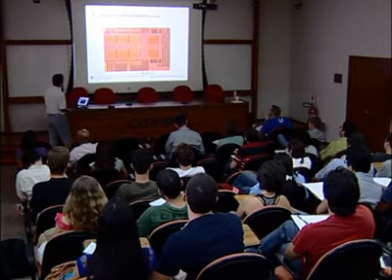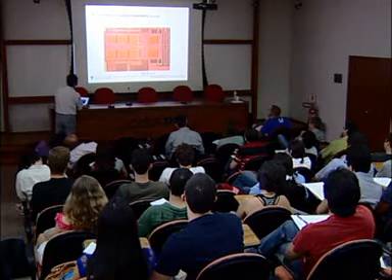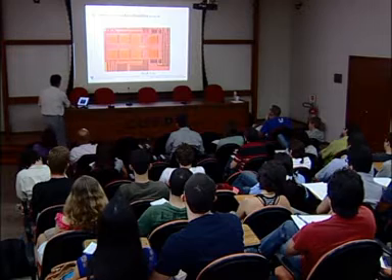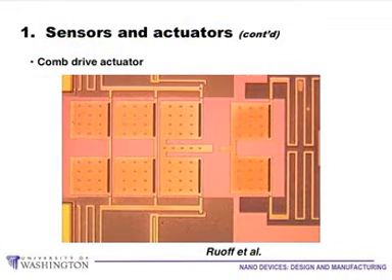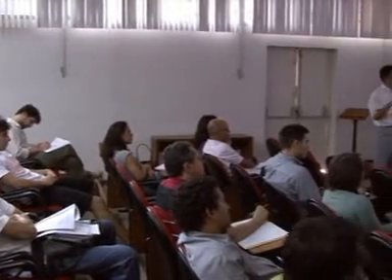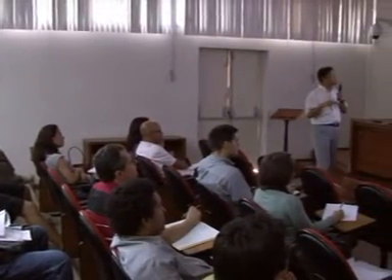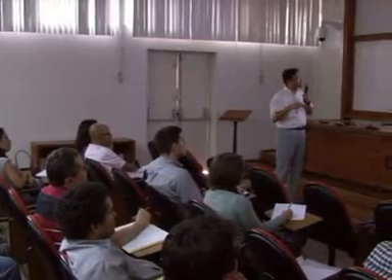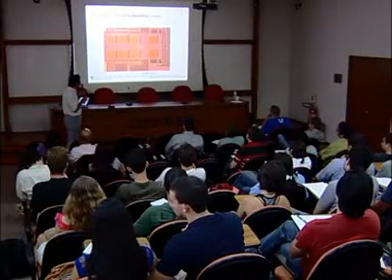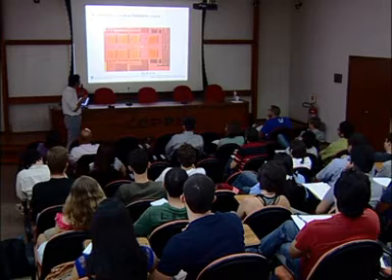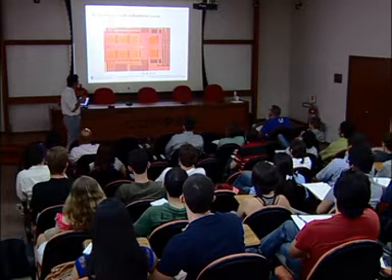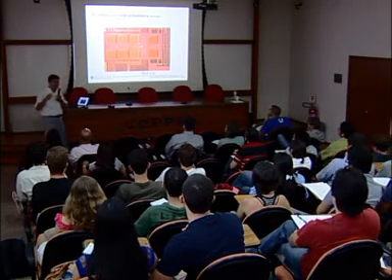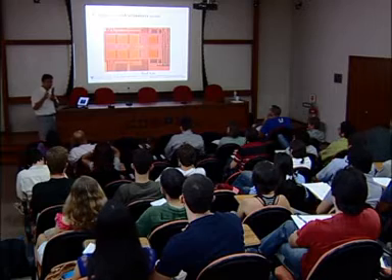Yeah, let's see some of a comb drive actuator. So this is a structure that I fabricated with my colleague when I was a student. The comb drive actuator is on this side, and it was attracted this way. And there is a hinge out there. So we wanted to install a kind of cantilever, like nanowires, in there. And then when the structure is released, we want to measure the elasticity of a structure. Okay?